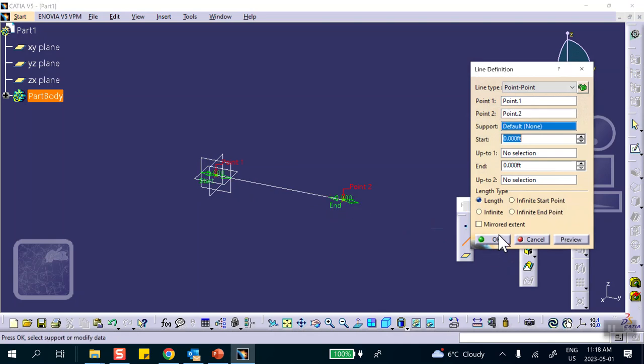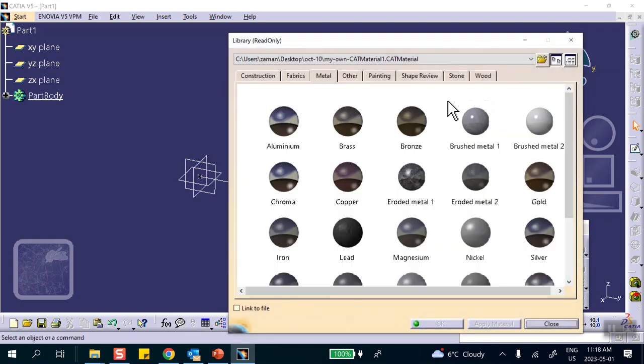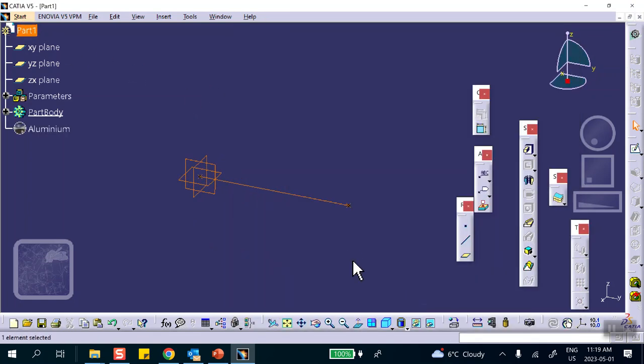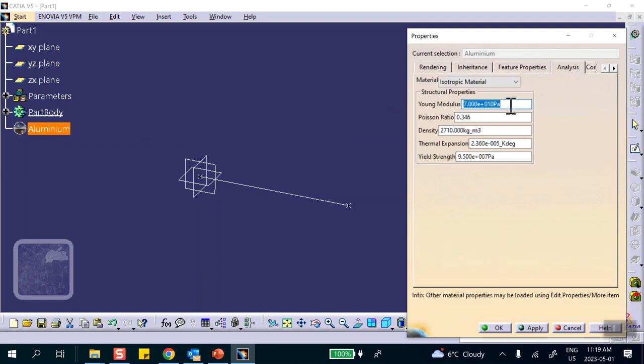These are pretty much the same steps that I'm doing in the previous videos on single degree of freedom and tricking Catia to do it, except that we're undamped. Now we're going to apply a dummy material on it. I'll use aluminum, however I'll change the properties of the aluminum so that they have very little stiffness and very little mass, so that they don't mess up the single degree of freedom calculation.